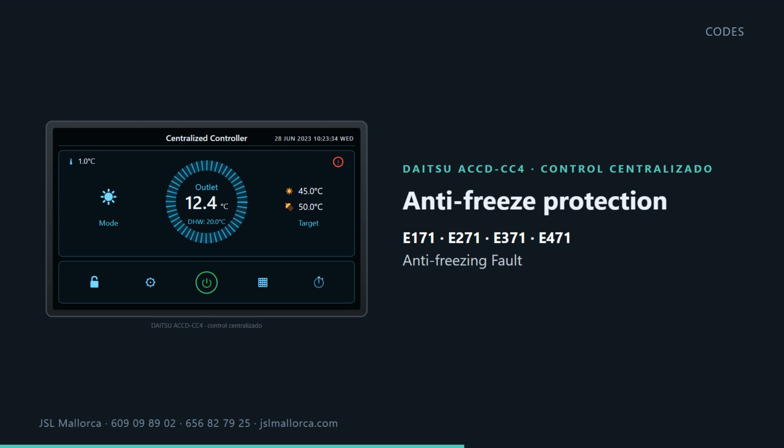Codes E171, E271, E371 and E471. Antifreezing fault. It happens because use side water system temp is low. Code E19. Primary antifreezing fault. It happens because excessively low ambient temp. Code E29. Secondary antifreezing fault. It happens because excessively low ambient temp.